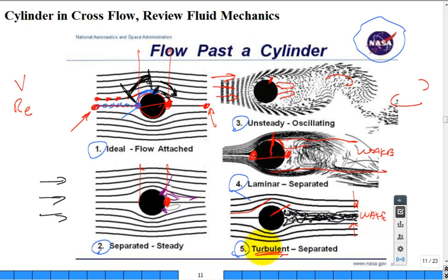Because the flow in the front side in here is going so fast, it can become turbulent before it separates. And if it's turbulent early on, it will navigate more of a severe curve and follow the sides onto the backside longer before it separates. It's because of the turbulence up in this region that the wake is smaller.